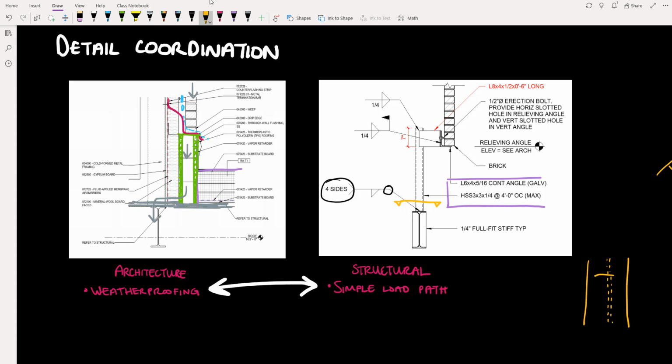And then the shape of our HSS, as I've drawn before, it's square in shape, but it has these curved corners. And as I mentioned previously, curving around a weld can be difficult. So if we were to weld all around, that would mean that they would have to weld those rounded edges, which can be tricky. So instead, we simply weld along the 4 straight sides and leave out those curved corners.